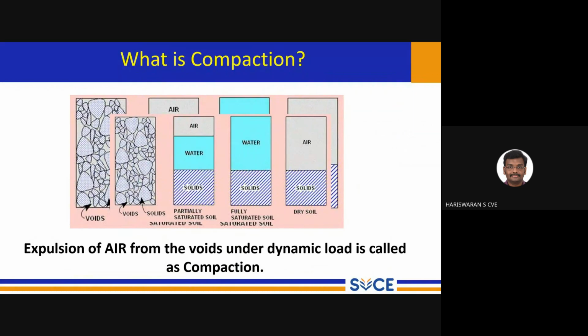That remaining amount can be found in the laboratory by executing the Proctor compaction test and the modified Proctor compaction test, right? In a mold, we apply a standard energy, and we see what density is achieved for the applied energy for the added water percentage, and then we change the water content.